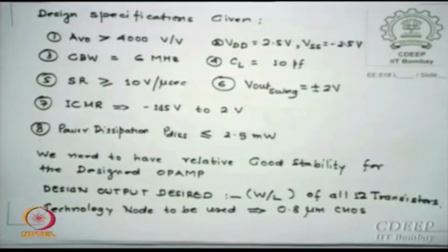2.5 VDD, -2.5 VSS is available for 0.8 micron, 5 volt swing. All 0.8 analog circuits allow you 2.5; actually, the smaller the node, the lower the voltage, and 0.8 is almost close to 1, so it is anyway higher. Why do I choose 5? Because we are not using it, it is a short channel device, so some effects of short channel are seen, which in our calculations we will not use; SPICE will take care of many of those parameters.